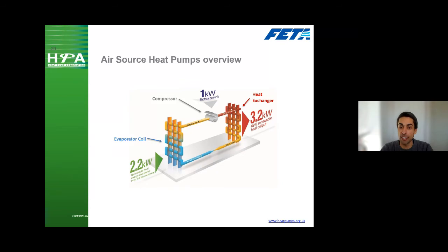It's important to say, yes, it is going to be a little bit cooler than perhaps what you might have been used to designing systems at, and that will mean that radiator sizes need to be thought about in that design phase. But it should be no less than what we should be doing for condensing gas boilers.